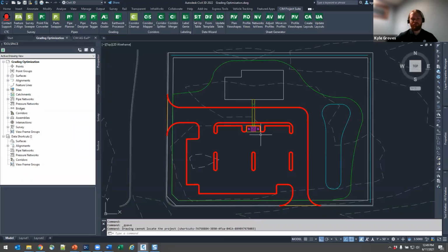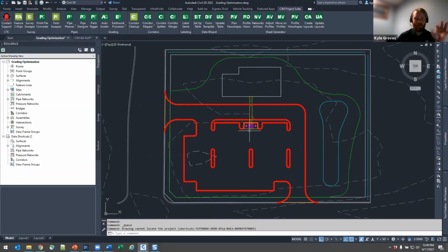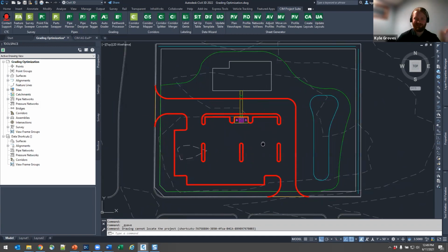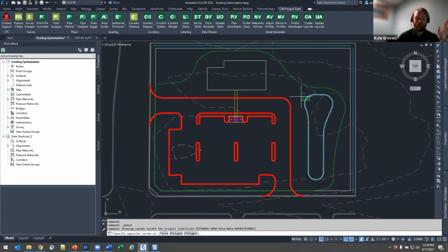Okay, so very similar, or it's the same site. I had to change the curb a little bit to make my accessible areas a bit more practical for this tool, an organized layout. But we've still got a detention basin on the east. We have curb and gutter line running through our main area, a building pad, and some daylight limits.